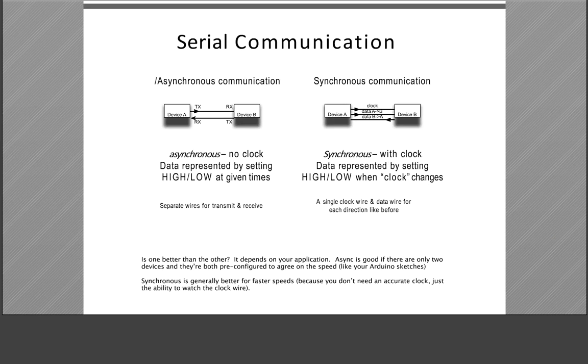USART was a universal synchronous asynchronous receiver transmitter. But in AVR we also have UART. UART means universal asynchronous receiver transmitter. That's right, only asynchronous. We don't have a clock in the UART of Arduino.